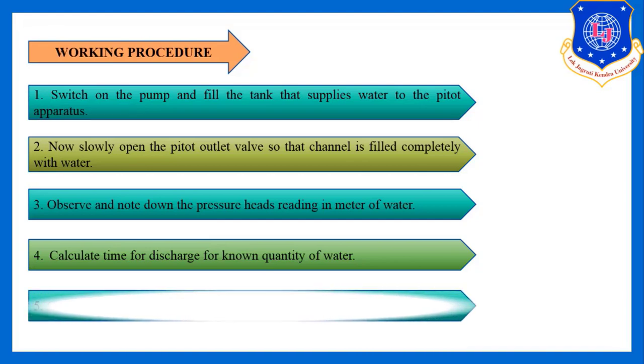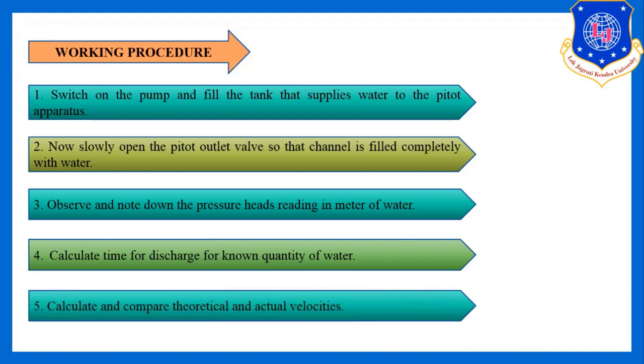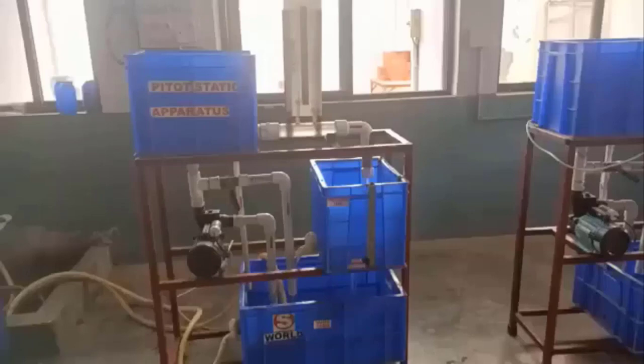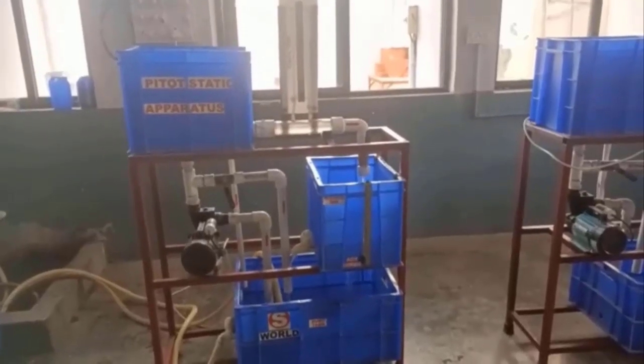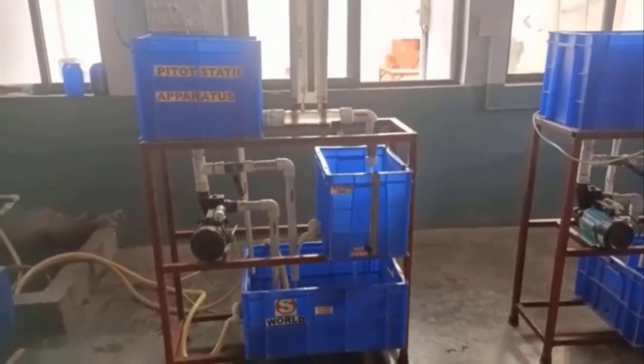Right? And in the last step, with the help of the pressure head reading and the discharge of the water, we can calculate and compare theoretical and actual velocities. Right? So these are the steps for the experimental procedure. Now let's see the working video of the experiment.